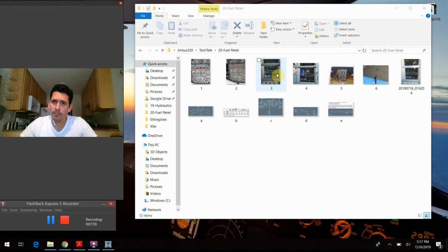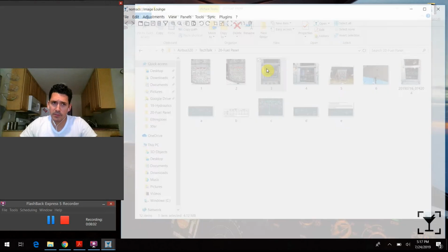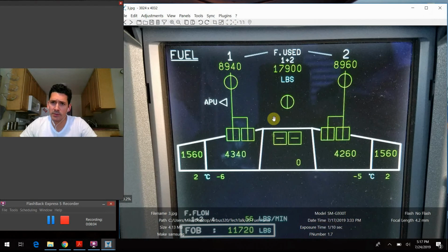So let's pull up our basic system display here once again and take a look at some of these things in a little more detail and talk about them. So in each wing we have two AC electric fuel pumps. That's what these box symbols are right here. We have two also in the center tank. These are, I guess, kind of the main way that we feed fuel under low pressure out to the engines. So we have these 6 AC fuel pumps on board the aircraft.